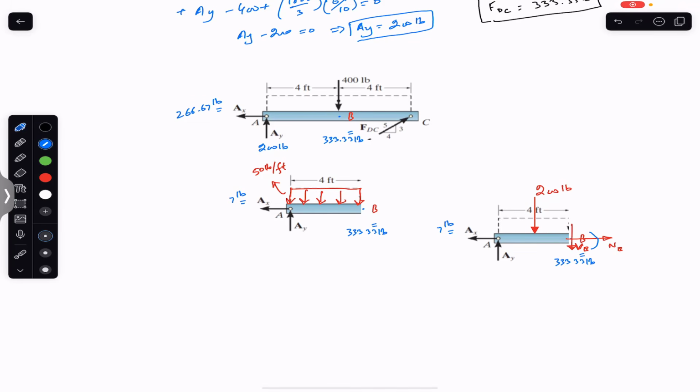And then we have to represent the bending moment at B. So again we have to draw according to the positive convention, and the positive convention on the right hand side of the segment for bending moment is in the counterclockwise direction. So this is our positive convention for the bending moment on the right hand side of any segment. So this is my moment about point B, that is the bending moment at point B. So this is when we are considering the AB segment.